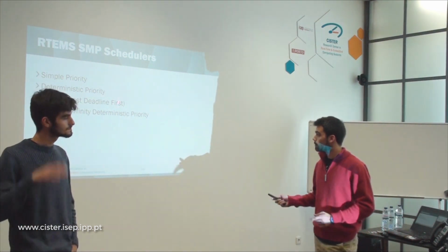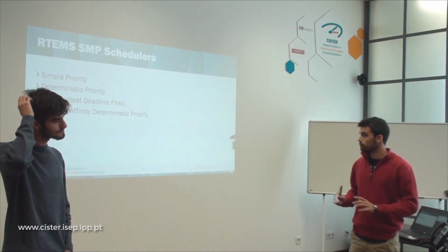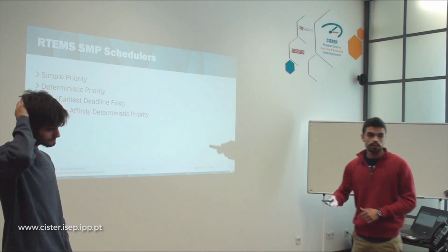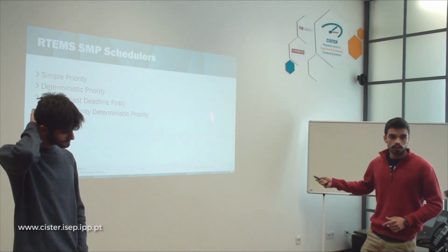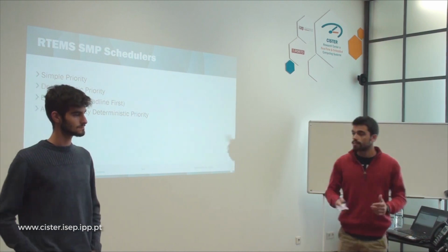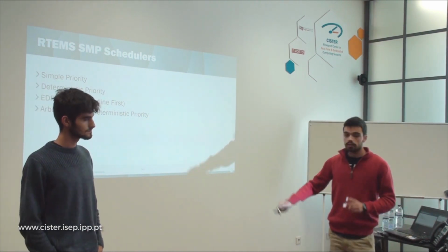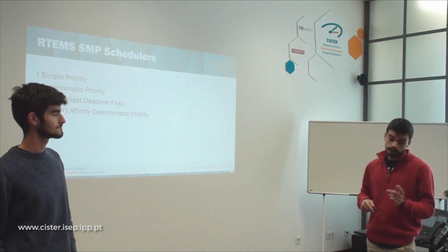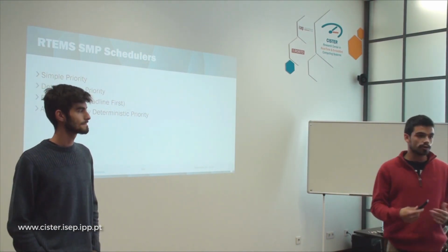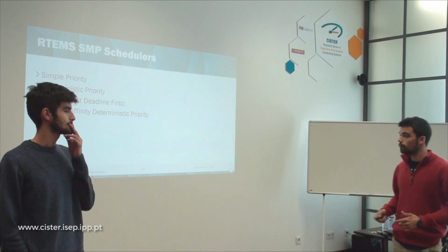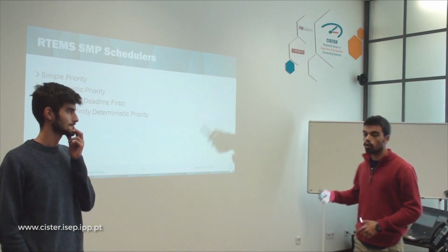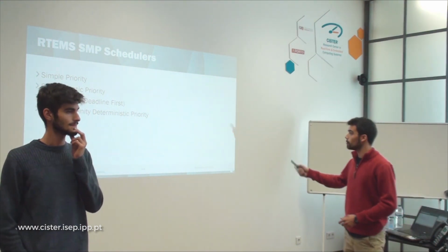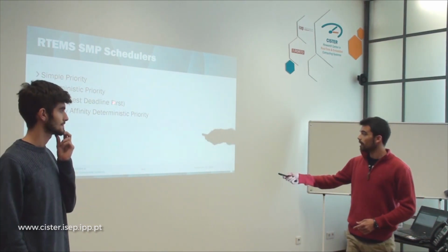As said before, for the use of periodic tasks, we had to join EDF with the rate monotonic manager to have dynamic priorities, since the EDF here can create 2 types of priorities. The background tasks are tasks that do not have any periodicity, that is, do not use the rate monotonic manager, and then we have the periodic tasks that are created with the rate monotonic and are scheduled by our EDF.